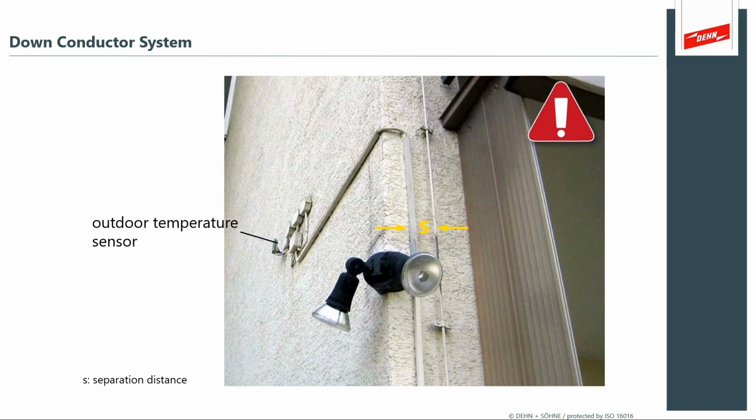So what's important about this photograph and the illustrations is that you now have a down conductor system and you want to watch for everything around it. It looks convenient to run a down conductor down that portion of the building. It's out of the way, it's not being touched by the neighbors, and it's not a high traffic area. But in this case the design's separation distance is so close to that electrical wiring that it's almost certain to flash into that circuit.